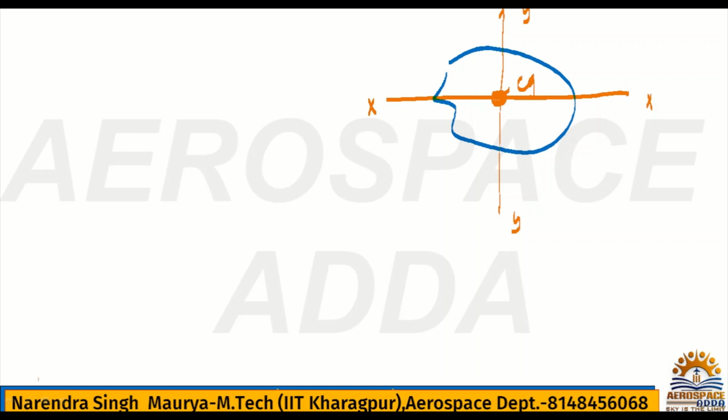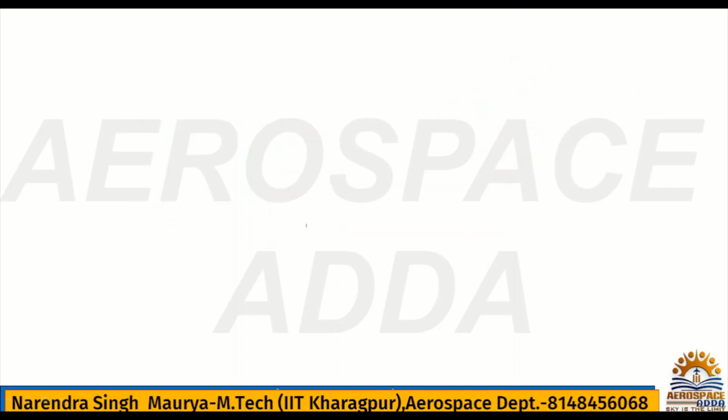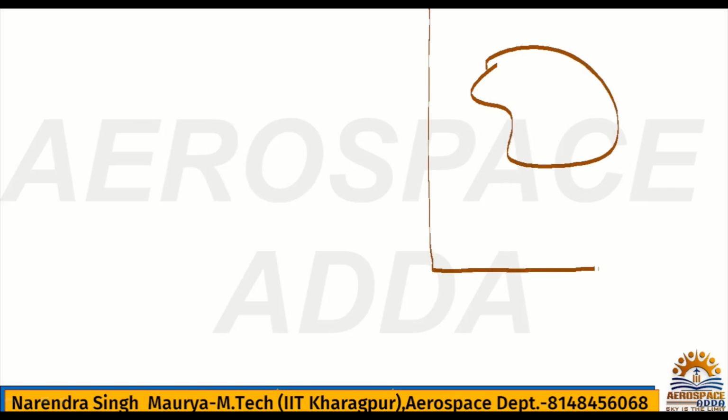If CG is here, then only you can write Ixx is the integral of y square dA, and Iyy is nothing but the integral of x square dA. That is true when the axis is passing through the CG, then this is the formula. But suppose this object is somewhere else, and I'm talking about this axis. My axis is now changed. Now this is the x axis and now this is the y axis.